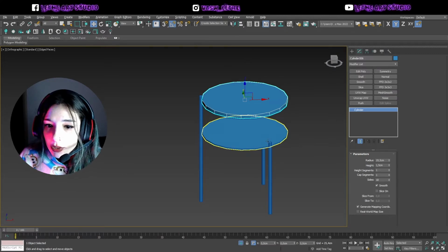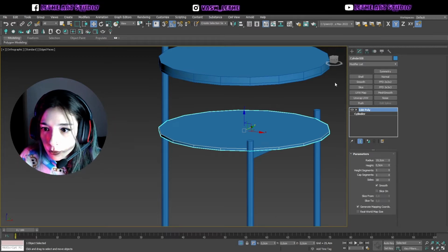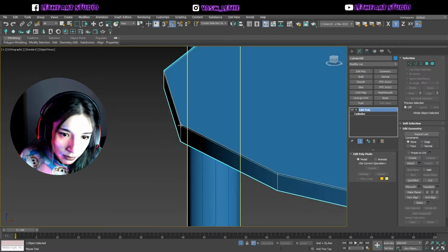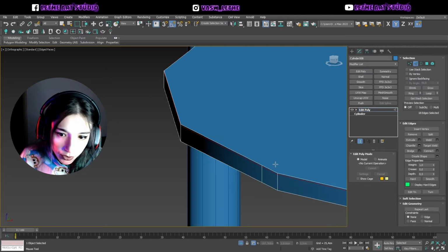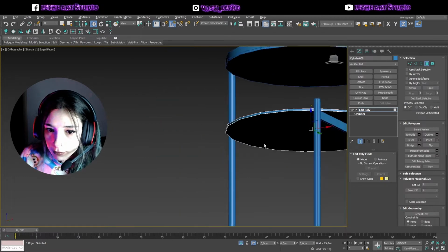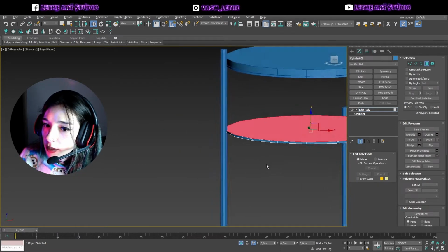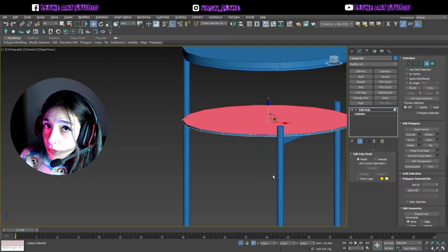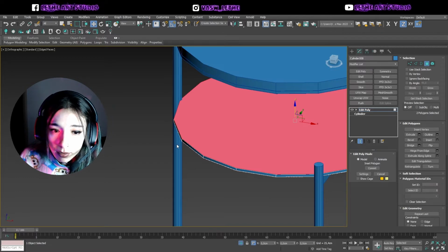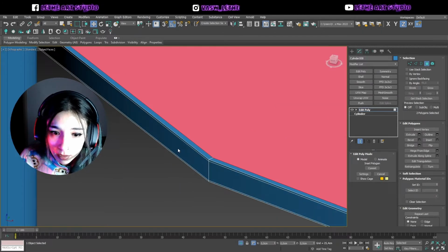And now, of course, the time has come for some mesh smoothing. And I'm adding the loops, horizontal ones, and the ones for here. Grab the top and the bottom of the surface of the geometry, and inset just a tiny little bit, even smaller.